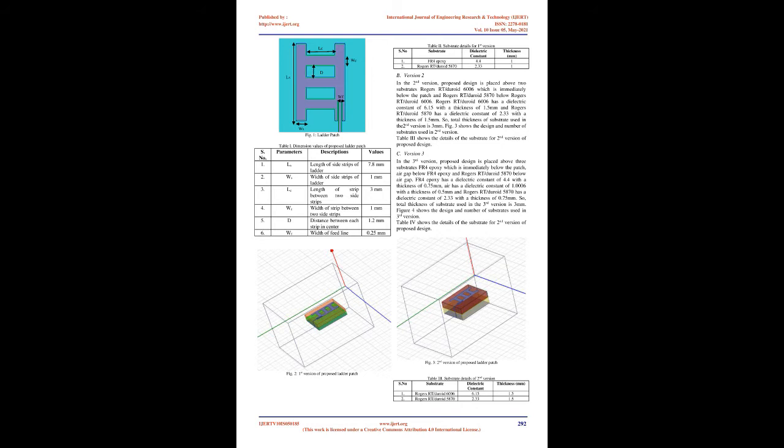A typical microstrip patch antenna would consist of a substrate, a conducting patch, and a ground plane. The dielectric substrate is placed in between the conducting patch and the ground plane, where the patch is printed on top and the ground plane is printed at the bottom of the substrate. Patch and ground plane can simply be understood as positive and negative terminals respectively.